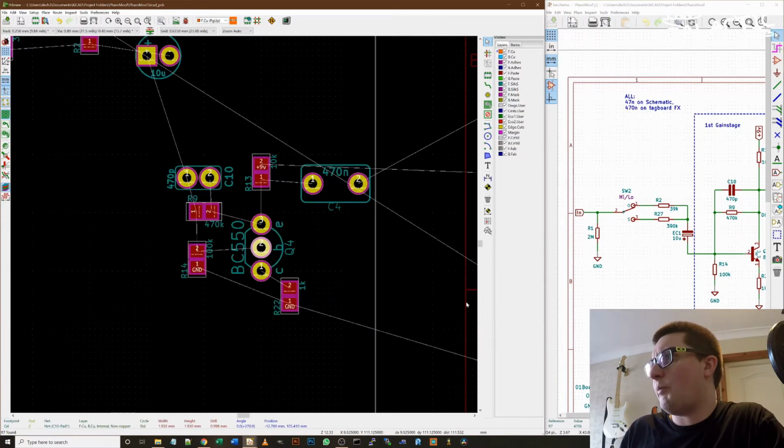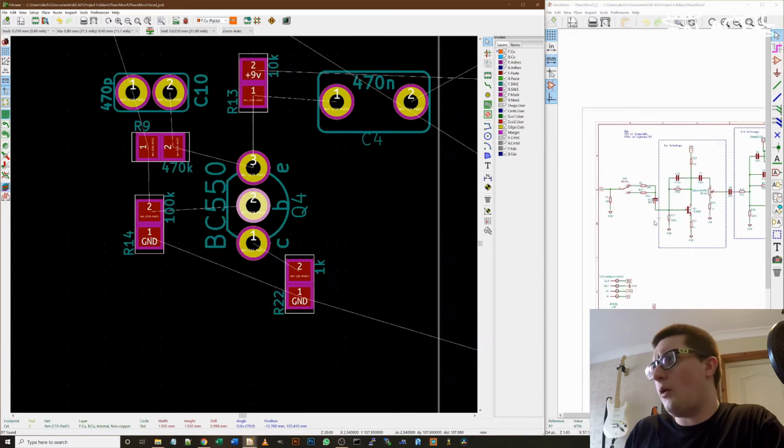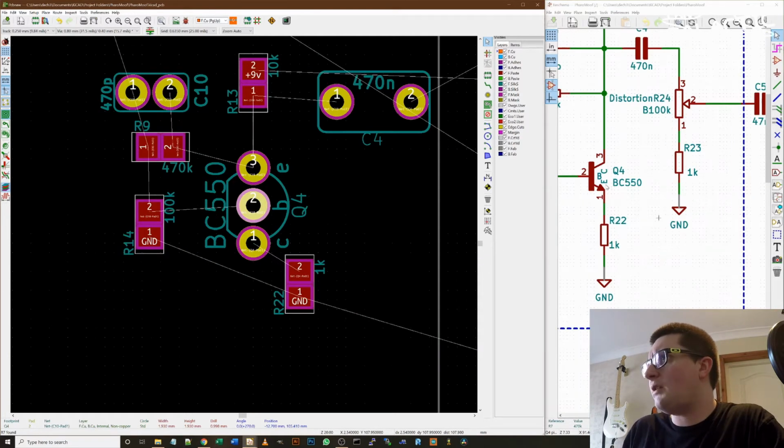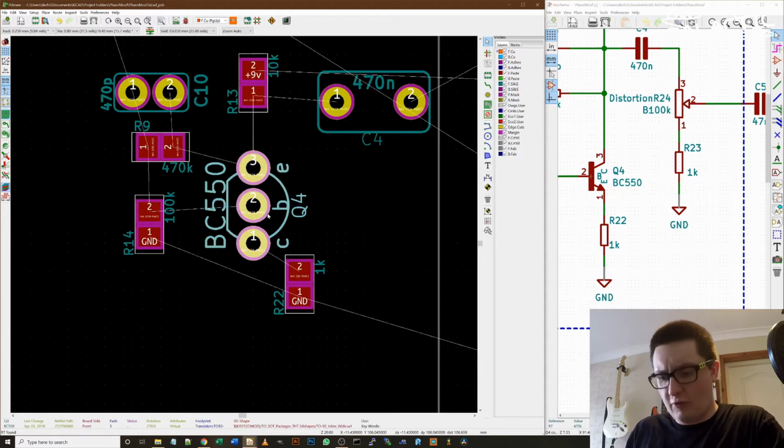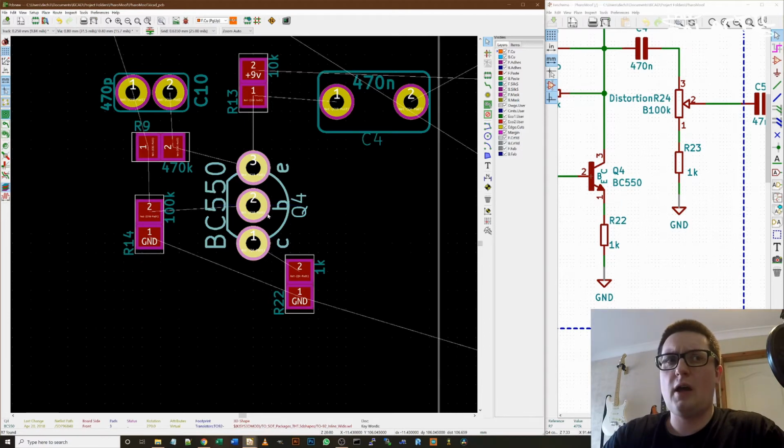Now, I've noticed a problem. On our board, pin 1 is labelled up as E, and pin 3 is labelled up as collector. Now, on here, I've got pin 3 is emitter, and pin C is the collector, which seems wrong. So my best option really with this is to get the transistor out that I'm expecting to use and test the pin out on it to see which way round the pins go, and then we can edit the part and make the pins match the schematic.